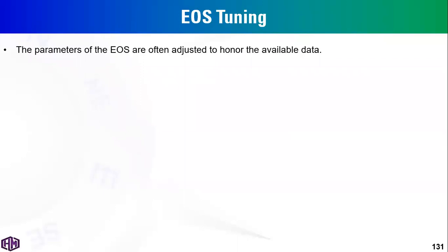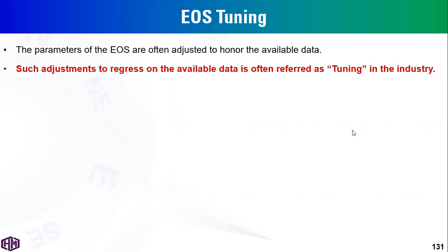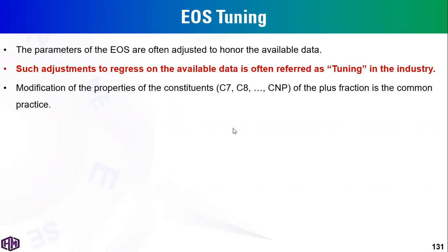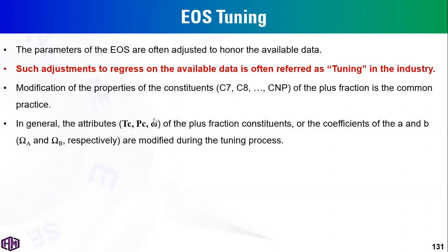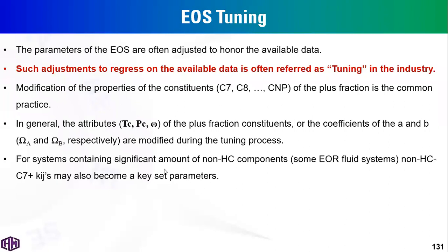So finally, once the PVT data and lab experiment data are evaluated and quality checked, and we ensure we have consistent PVT data and consistent lab experiments, we can go to equation of state tuning by changing some equation of state parameters like the critical pressure, temperature and the acentric factor for the heavier components, heavier than C7 or C6 and so on.